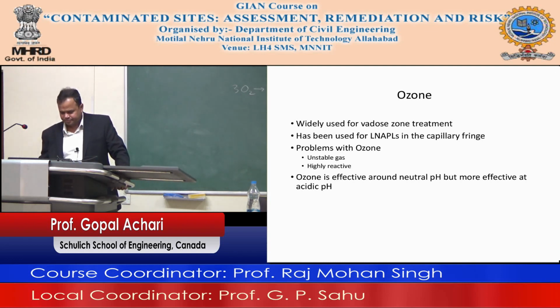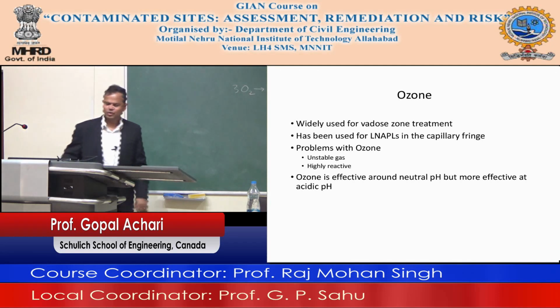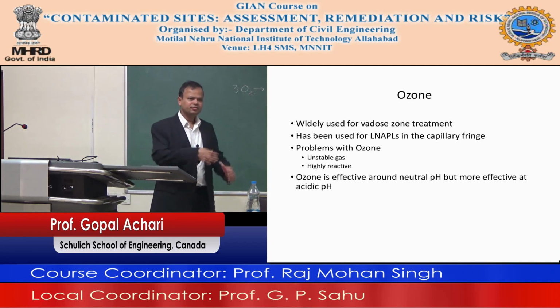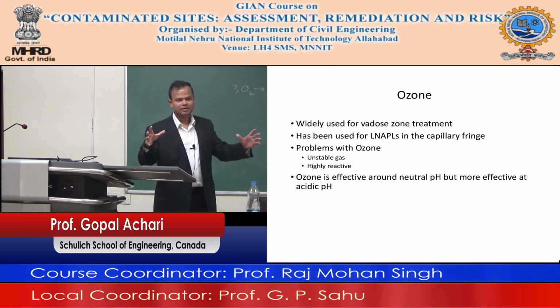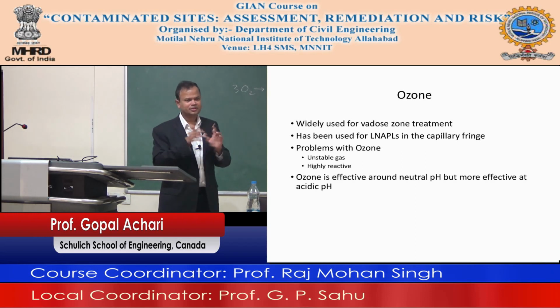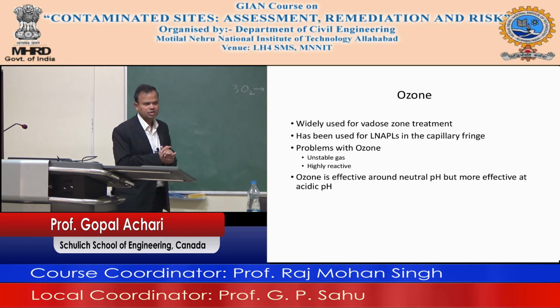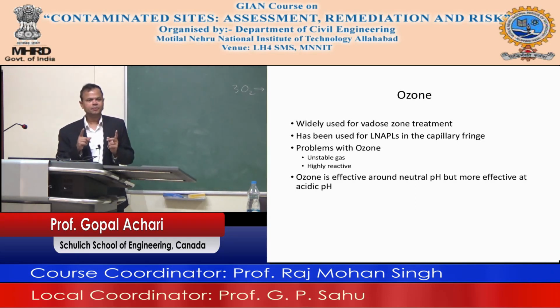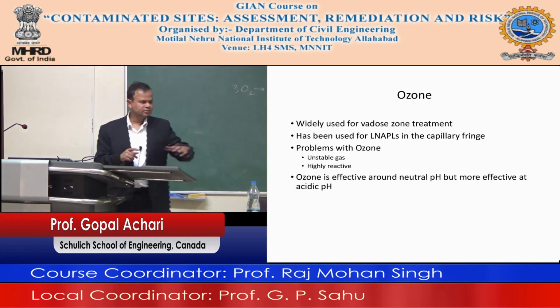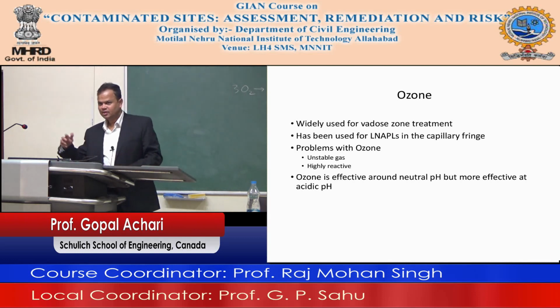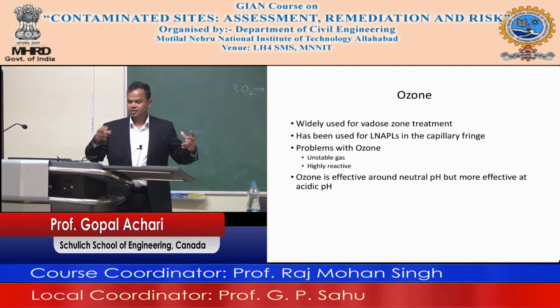It has been used for vadose zone treatment. Remember, it's a gas, and if you have hydrocarbons in the vadose zone, you can inject it and it will do the treatment. The problem is you want to make sure that the ozone does not get into the neighbor's house, or that somebody is standing there at a crack.